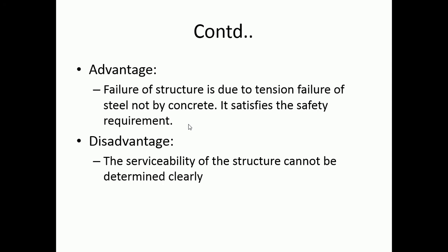The disadvantage is that the serviceability of the structure cannot be determined clearly. Why? Since we are designing the structure for ultimate load, predicting cracks will be a little bit tedious for us. Because of that, we cannot give a standard assurance for the serviceability case. So this is regarding the load factor method.